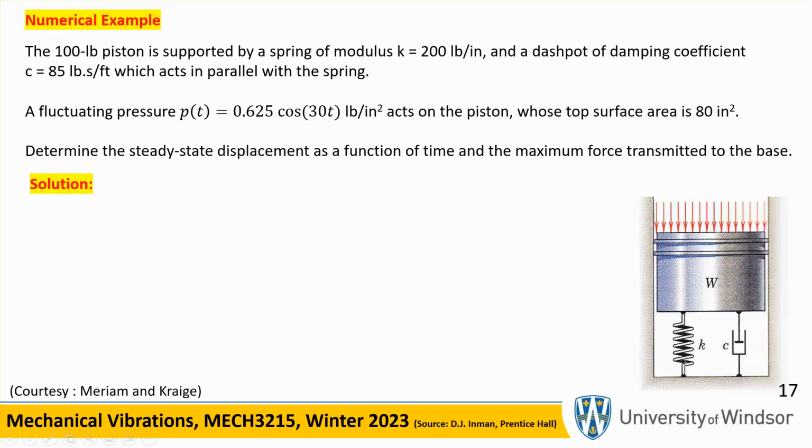However, what is this K? This is probably your connecting rod. Your connecting rod provides some kind of a stiffness, some kind of a resistance to the motion of the piston. So I'm just giving you an example. We draw a K here, but we don't actually literally have a spring in there. The other thing is that we don't have a damper there. What we do have, probably because of the friction on the side, you find an equivalent viscous damper, and that's what you're going to do in 2 weeks, and you assume that actually there's a damper there.